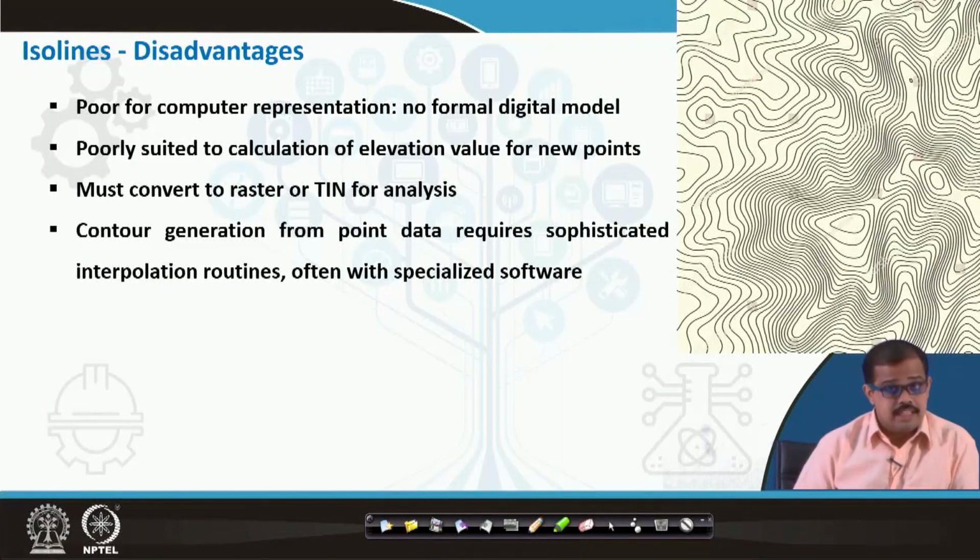But there are certain disadvantages that people have to look at. Some of them: it is poor for computer representation, so you do not have any formal digital model supporting this. It is also poorly suited for calculation of the elevation value of a new point. If you are trying to calculate the elevation of an unknown new point, then it is quite difficult.